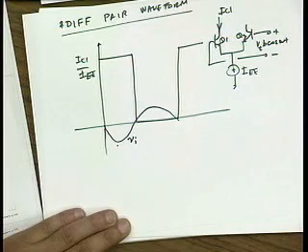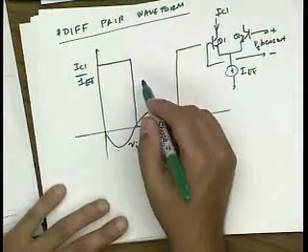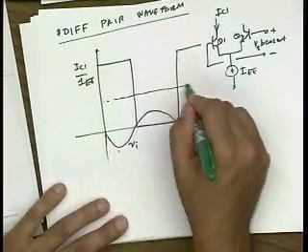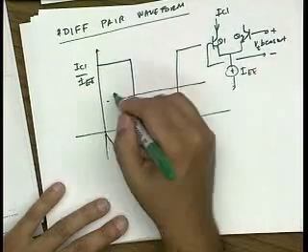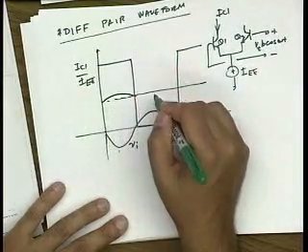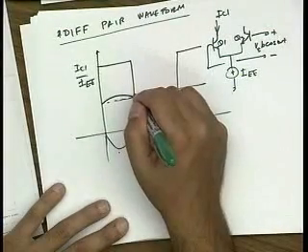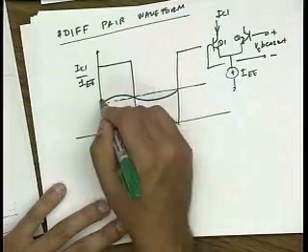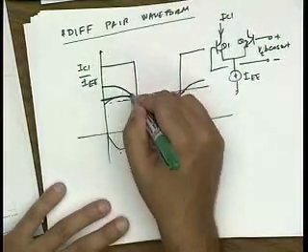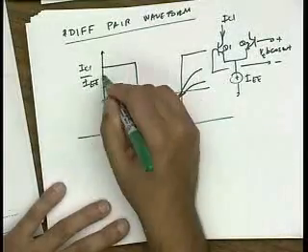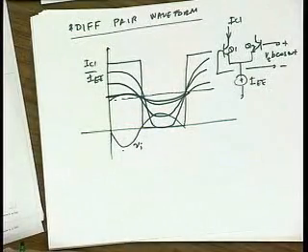And as you could imagine, as you lower the input voltage, if you make it very small, then the average current through here is basically IEE over 2, and it would be a sinusoidal kind of signal. And as you increase the amplitude more and more, actually, sorry, this is a bad drawing. It looks like this. As I increase the amplitude more and more, it would tend to approach the square wave in the limit. Okay?